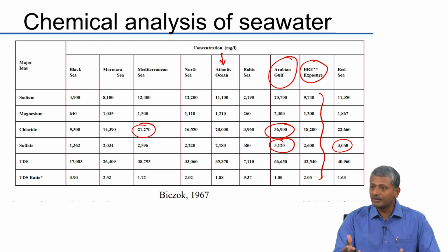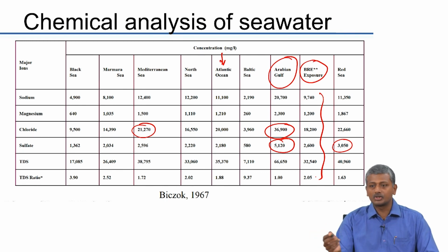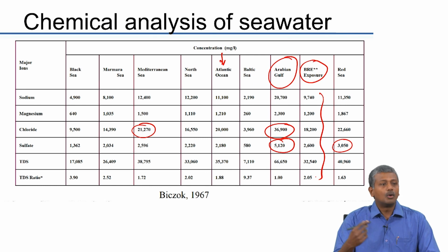So, we owe a lot of our codal regulations to the research work that was done over a period of 20 to 30 years at BRE. Most of those values we see, water cement ratio less than 0.4 or 0.45, all that is arising from this long term research study performed at BRE.